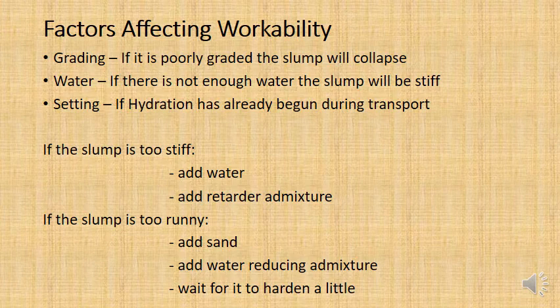What happened? Well, the hydration reaction was already taking place and the concrete was already beginning to set. So that can affect workability over time after mixing because of the setting.